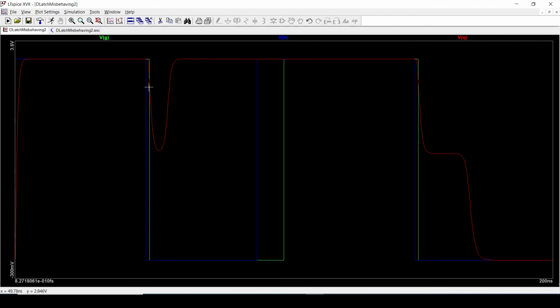In this case, the value at the output hadn't quite reached the halfway mark, and so when the discharge current has turned off, it just turns around and heads back to a logic 1 because it hadn't passed the halfway mark, so to speak.